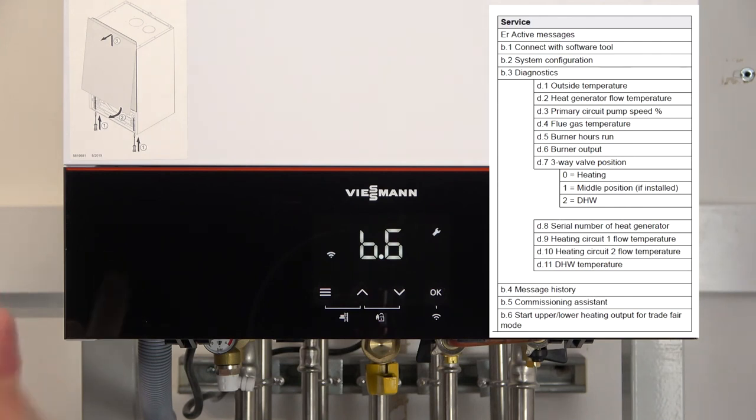The reason we do that is because if you've chosen this combi for your 35 kilowatt option for your high hot water delivery, but it's in a smaller property with a heat loss of 4 kilowatts, then you can range rate it down to 4 kilowatts. You wouldn't want to send 32 kilowatts of heat down to that 4 kilowatt system. So that's the reason why we've done that.